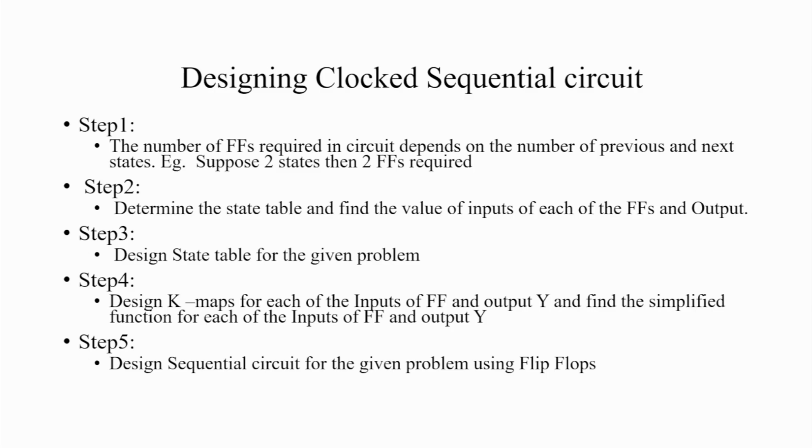First, find how many flip-flops are required during the design of a clocked sequential circuit. The number of flip-flops depends on the number of previous states and next states. Suppose we find the value of A(t+1), which depends on the values of A(t), B(t) and input X.